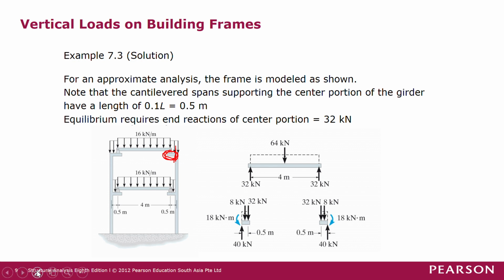So that will give us a free body diagram like this. When we cut across a section here, there should be a support reaction there and a reaction moment over there. So these two values are not known in the first place. Take note that these two are unknown reactions.